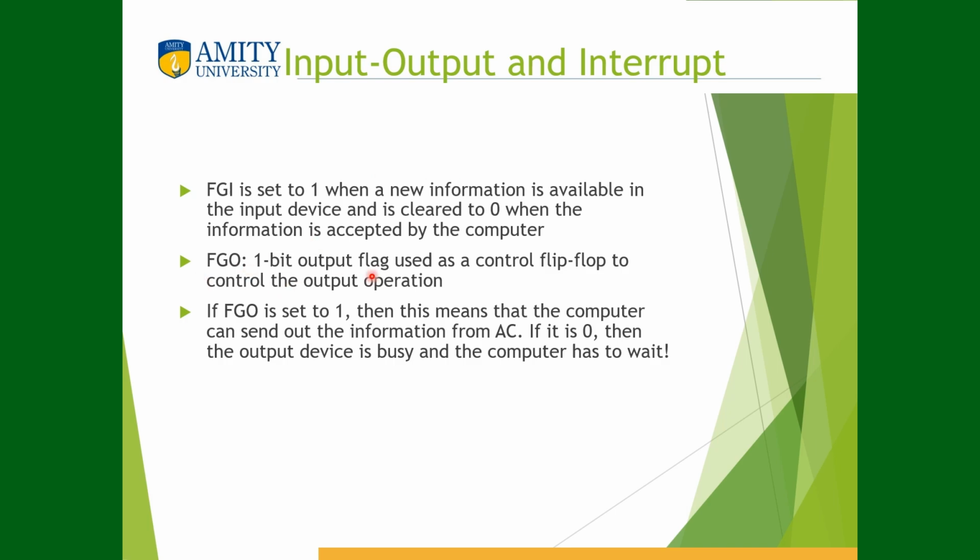FGO on the other hand is the output flag. It is a 1-bit flag again. It's used to control the output operations. If FGO is set to 1, this means that the computer can send out information from AC, but if it is 0, that means the output device is already busy and the computer has to wait.